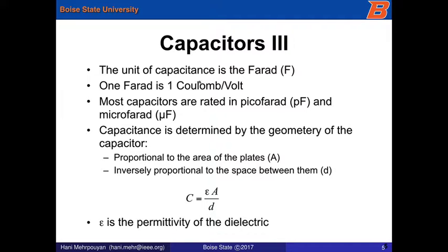So the unit of capacitance is farad, and 1 farad means that you will be able to store 1 coulomb per every volt. That is a very, very large capacitance, 1 farad. Generally speaking, when we deal with capacitors in electronic circuits, we will deal with capacitance in the range of picofarad to microfarad.